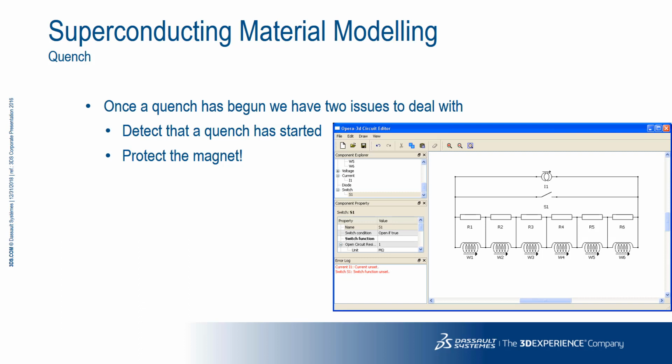This reduces the ohmic losses in the conductor, protecting the magnet from overheating and allows the cryogenics time to cool the windings. However, the reduction of current flow in the windings will cause a rapid quench in the fields produced by that coil, potentially causing neighboring coils to quench due to rate-dependent losses or losses in other conducting structures that oppose the field changes.